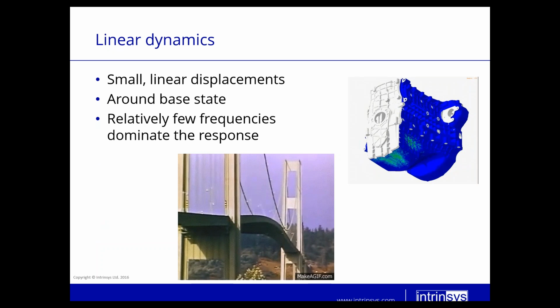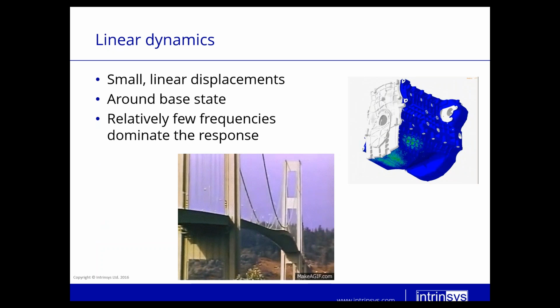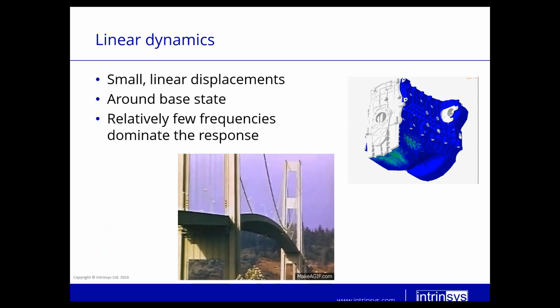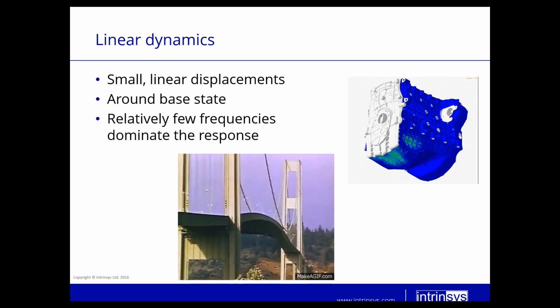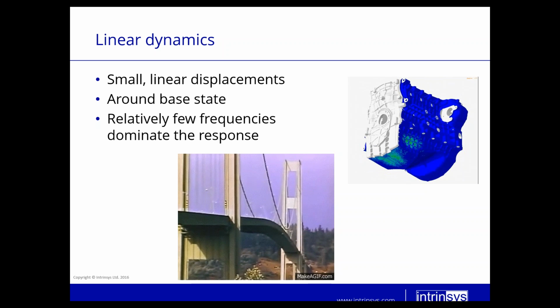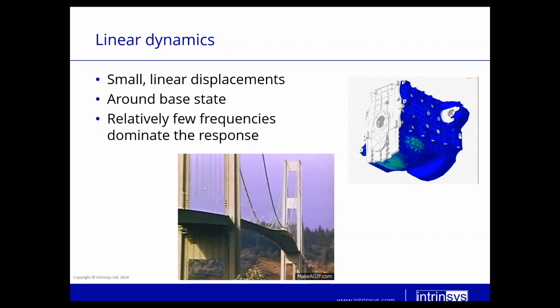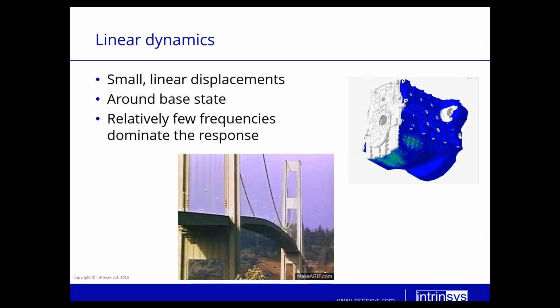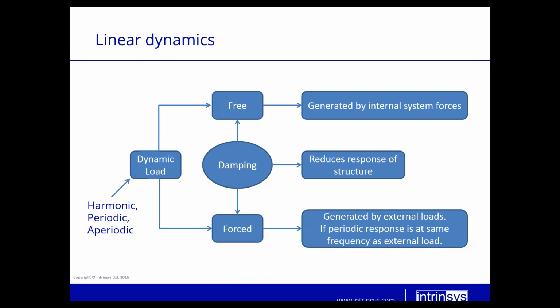So linear dynamics, we had an excellent webinar on this a few weeks ago. Just a quick recap. Linear dynamics is small linear displacements around the base state, and relatively few frequencies dominate the response of the structure. So we can work out those few modes, for example, and then predict the response by using only those few modes.